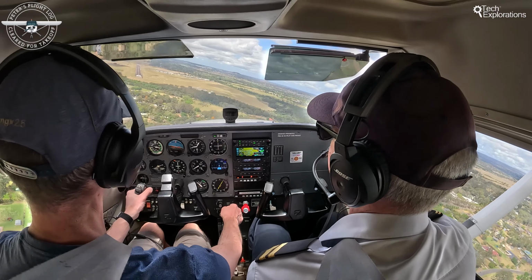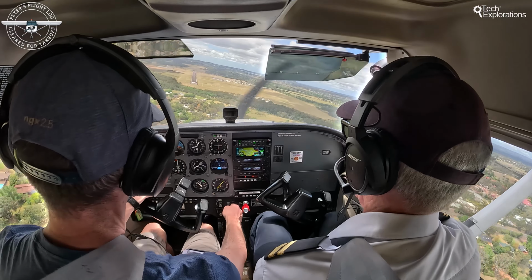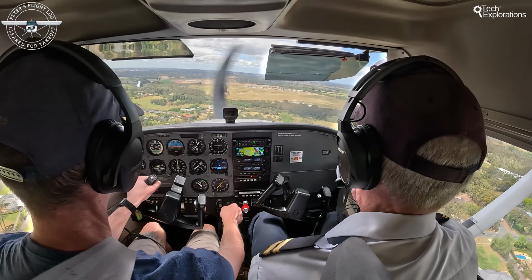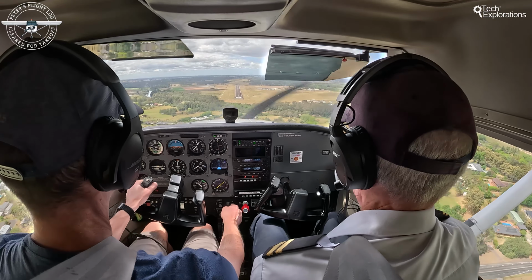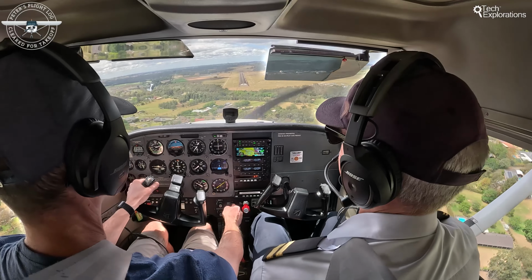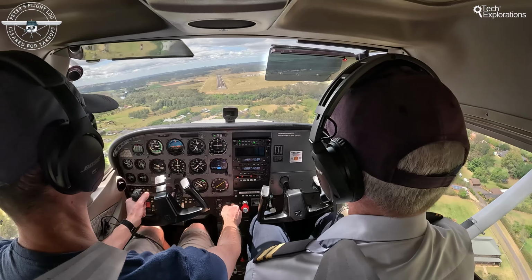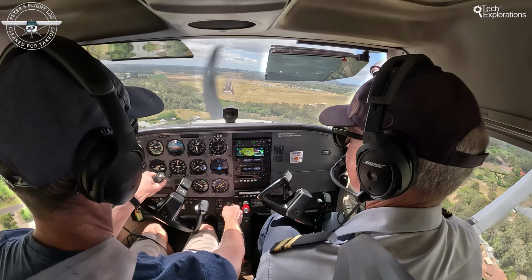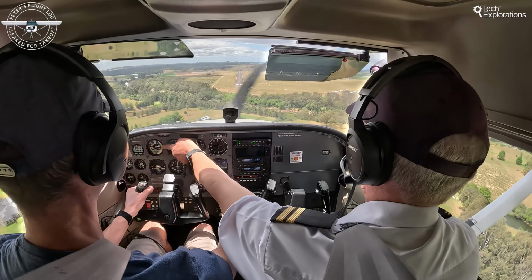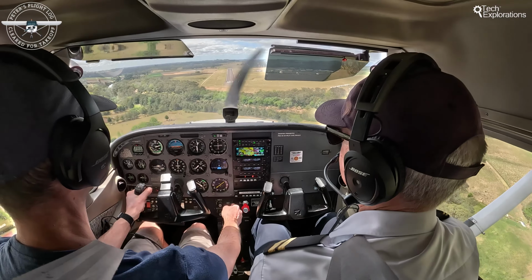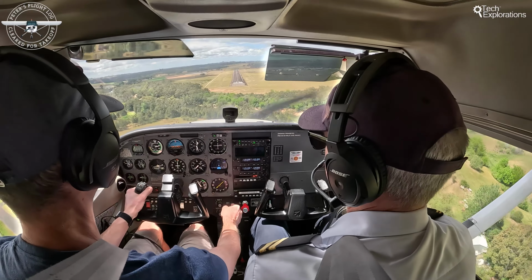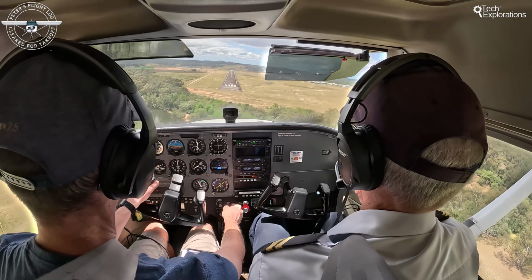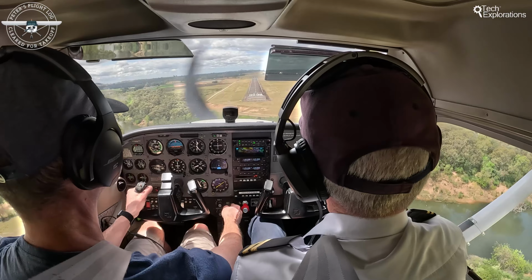There was one particular moment I noted in my mind to check in the video, when the plane tipped forward during a landing. I thought it was a tailwind to blame. However, checking the video evidence later showed that it was me, not the wind. So after going around, if not correctly established to land, I have a new permanent ingrained behavior. Never push forward over the runway.